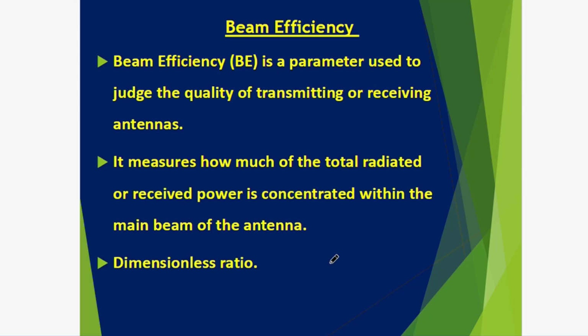Then what happens if we find that? If the efficiency is high, we can say the power is highly concentrated in the main beam, meaning there is no wastage of power in the minor lobes. That is the concept of beam efficiency.